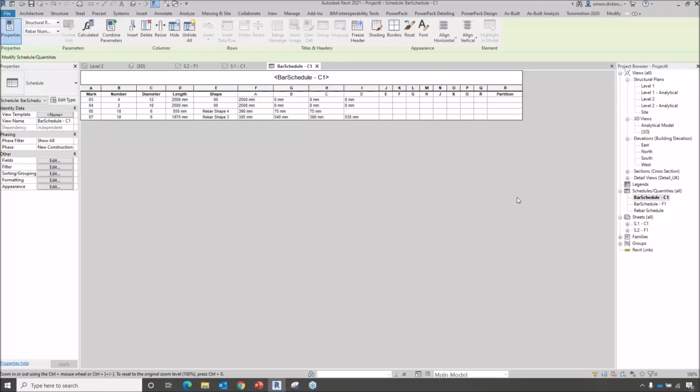So if I've already got a schedule set up in a project that's got all the information I need, then I can link that into that. And the other thing as well is, because of a template that I started with, you'll notice here that there's a small issue with my type 51s. So it's got the wrong coding, but there are ways to update that and get that information correct in there as well.